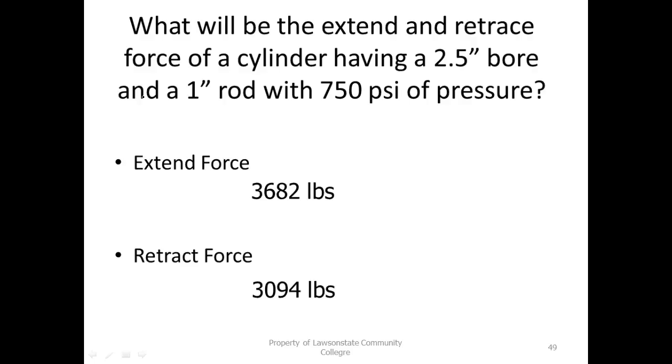What determines the pressure the pipe can handle is the thickness of the walls that keep that bore in there. So the size of the pipe determines the flow, or how fast things move. That's why in water pipes you have schedule 40 and schedule 80. What changed? The wall thickness. So one of them is rated at a higher pressure than the other, but we use lower pressures with pneumatics, and we'll look at that later on.